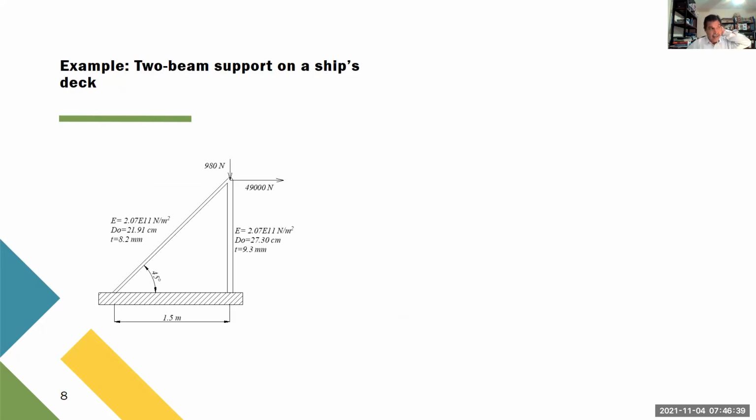Now, in this case, if you push this downwards and move this to the right, because of this action, this vertical beam will bend. Also since this is clamped, because of this force and this force, this also will bend. But because of this compression, this element will be in compression.